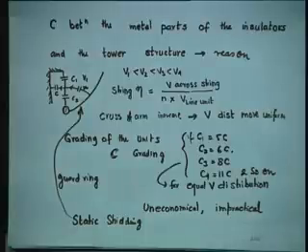If C1 is 5 times capacitance, C2 becomes 6, C3 becomes 8 and C4 becomes 11 and so on. Remember, we have talked about 19 piece suspension insulator. By the time you reach C19, it may be some 120 C. So, it looks so ugly. Each unit is so different than other.